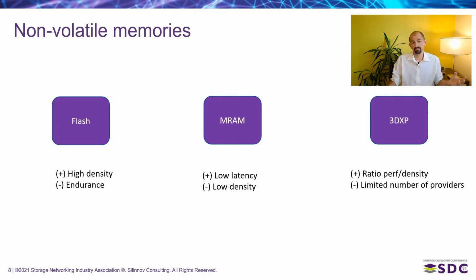There are also opportunities to use an MRAM in a computational storage device for a write cache function, okay? But also maybe for more specific applications. And I think about a deep learning system. If you want to provide deep learning acceleration, not with a GPU, but with a specific ASIC or FPGA on your board, then you need to store some parameters. Why not using the MRAM to store the weight of the neuron model in your device?